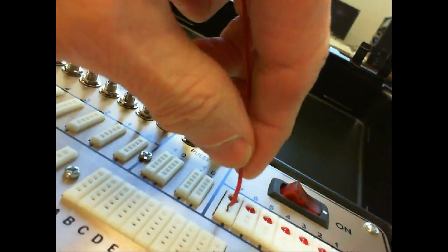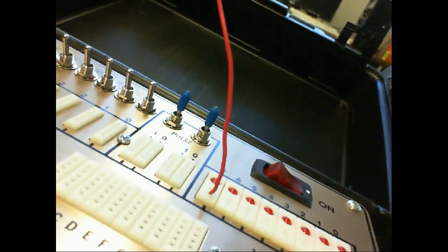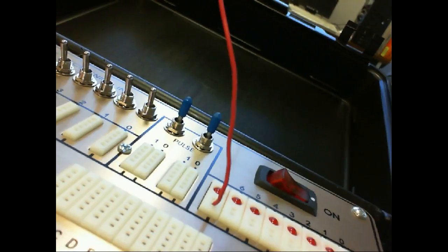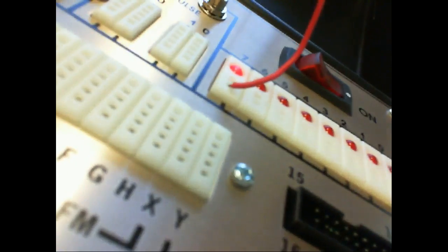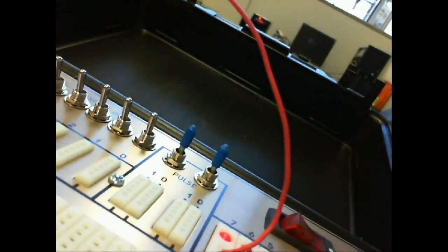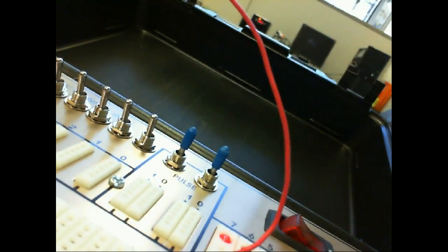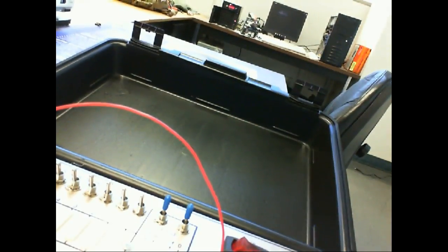So right now, this light emitting diode right here is off. You see that? So if it's off, it's probably seeing a what? Low. If it's on, it's seeing a high. That makes sense? Okay. So we'll be using this a lot more than we use a logic probe. Those are already available on the trainer. The only problem is that this doesn't tell us if it's legal or illegal.